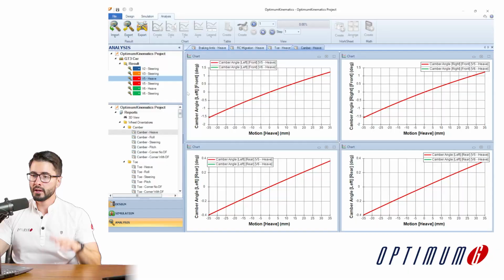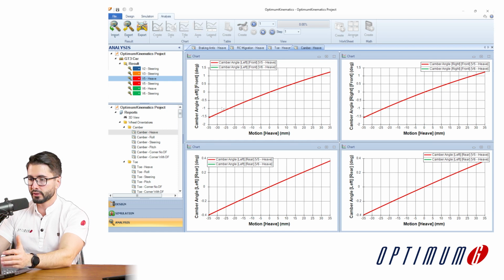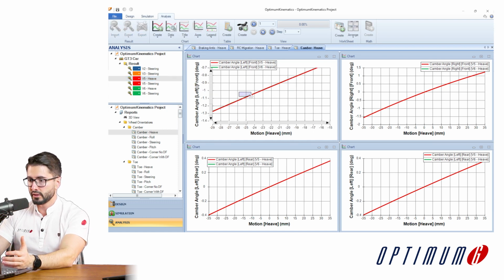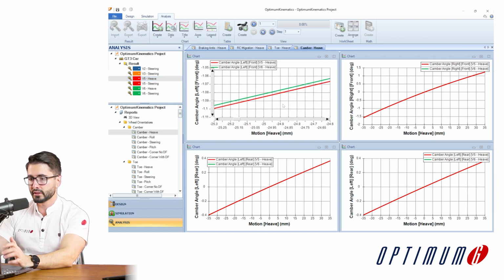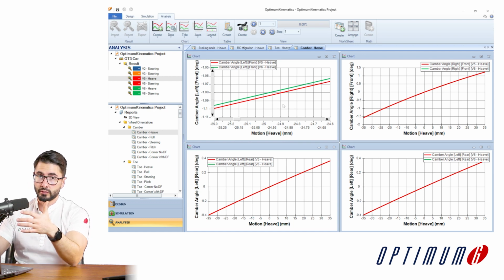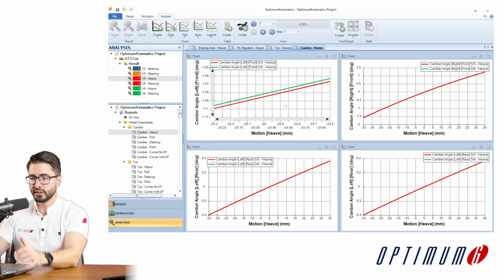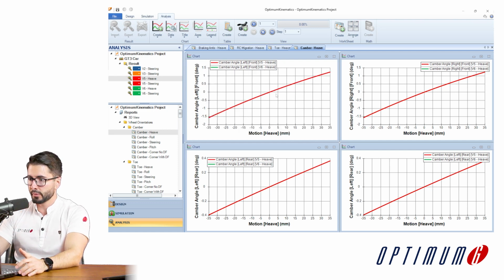Right, so now that we have V6, which adjusted Y and X coordinates, we were able to run simulations, and we are going to confirm that we do not see big changes compared to V5, even after the adjustments. So since we are changing the position of the wishbones, it is very important that we check camber angle variation, which is what we're checking here. And actually, after I plot both versions, the change is really minor. So as I told you, as long as the change is not large and that you also keep it within the plane, we should see a small variation. So that's very positive from the perspective of camber angle.